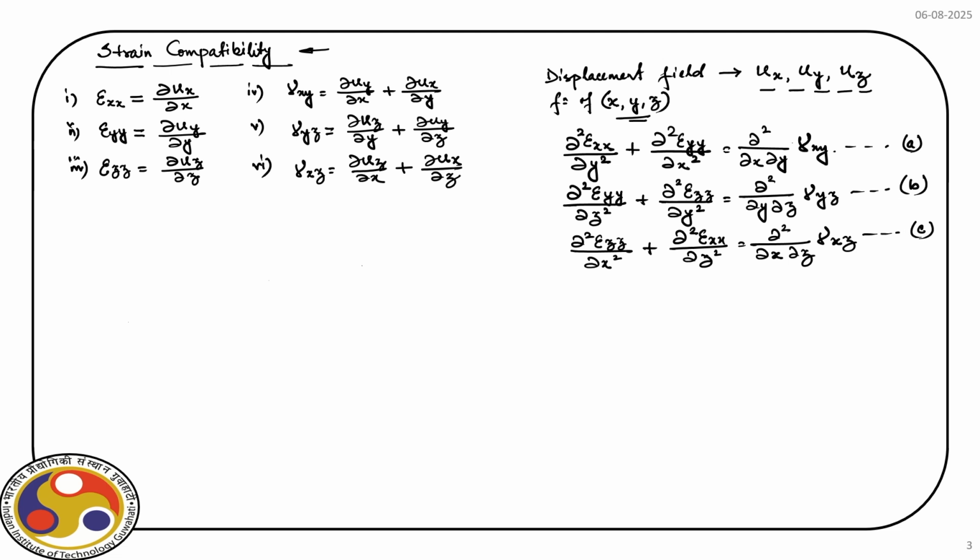If I follow the same logic, what I see for the shear strains, again if you look at gamma xy, it has ux, uy differentiated appropriately with respect to x and y. Similarly, in other components also we have the same displacement field appearing. That means, again, before deriving anything, we can expect that there is interrelation between these shear strains, and let us investigate that.